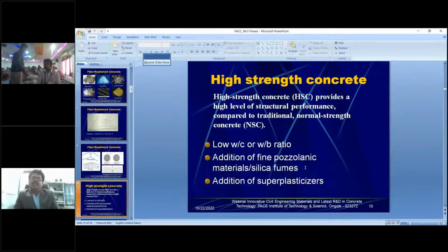See, only if I use cement to develop the strength, then automatically it is not going to be economical, and there is even a burden on the concrete. If only cement is increasing, then you are going to see so many other problems. But if you utilize this binder, because it is a byproduct, if you take fly ash or GGBS or anything, it is a byproduct. So if you utilize this, you get two ways of solution to the problem.